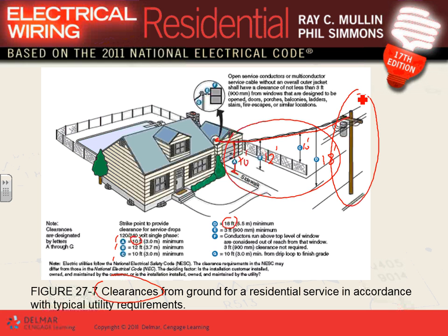The only way we can control is this area, the mast. So if here's the building, guys, I can put a 1-foot mast stick off the building, or I can put 3 feet, or 10 feet. So if you need more clearances, you start increasing the height of that mast or pipe that's going out. So be very aware of that one.